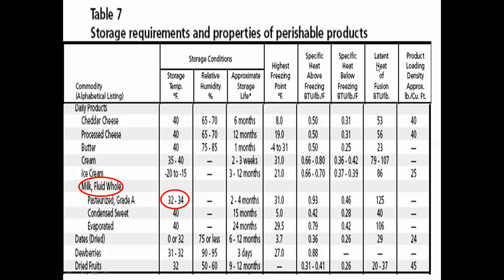Here we don't want to take latent heat because there is no change in the phase. So leave this one. Now we are dealing with specific heat, correct? Or we could call it sensible heat also. So the specific heat below freezing. Are we bringing the milk below freezing, below 0 degrees Celsius? No, right? So we can cancel this also. Specific heat below freezing. We are not freezing it. We are just cooling only.